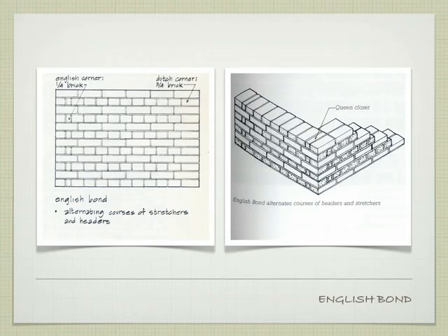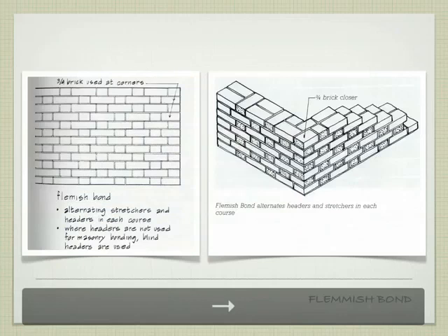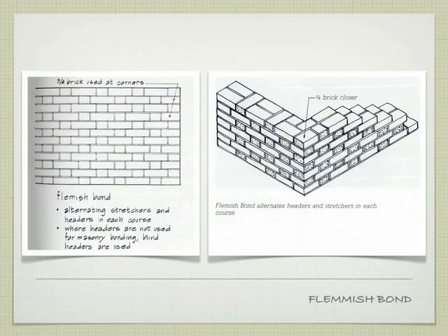So now we have a wall that's 2 wythes deep that's actually being tied together and working as an integral structural unit, as opposed to just a skin or a veneer on the building, right? And so the rest of these variations are all variations but are doing basically the same thing, where they're trying to tie the 2 wythes together and the courses together, right? So a Flemish bond looks slightly different because we don't have a standard running bond in any of the rows, right? Every other brick is turned, so it's very integral on every level, on every course, right? They're tied together.